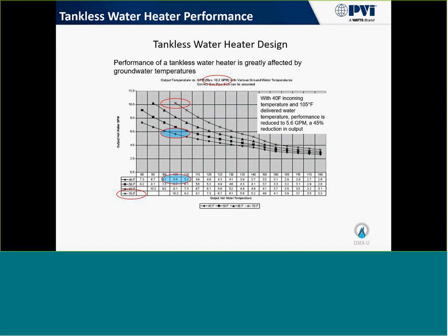They have to be within a certain range of pressure on the cold and hot incoming into those valves in order for them to function properly. So we've run into a few headache scenarios where the mixing valve performance is drastically affected by the tankless water heaters installed in that system, and it changes seasonally.